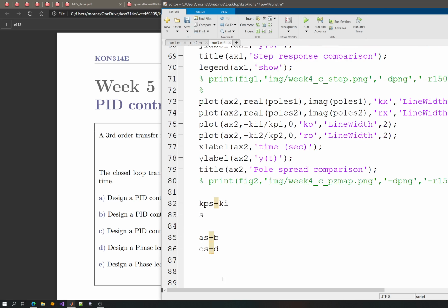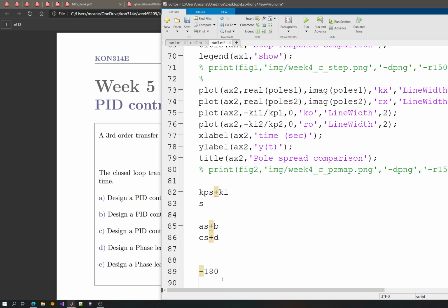If you remember, we had an angle condition: if a point in the S domain satisfies the minus 180 or positive 180 degrees angle condition, it is on the root locus of the G(S) transfer function we are examining. If it's, let's say, minus 250, we need to add 70 degrees to it, so it should be on the root locus.